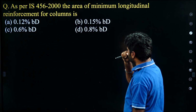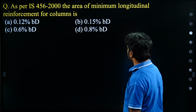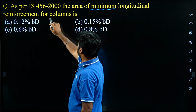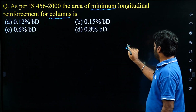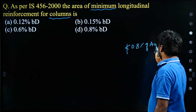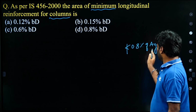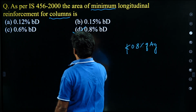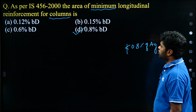As per IS 456-2000, the area of minimum longitudinal reinforcement for columns is, they are asking in columns. In columns, the minimum reinforcement should not be less than 0.8% of the gross cross-sectional area of the column. Suppose if you take a rectangular column, then the gross cross-sectional area becomes BD. Here 0.8% of gross cross-sectional area. Next question.